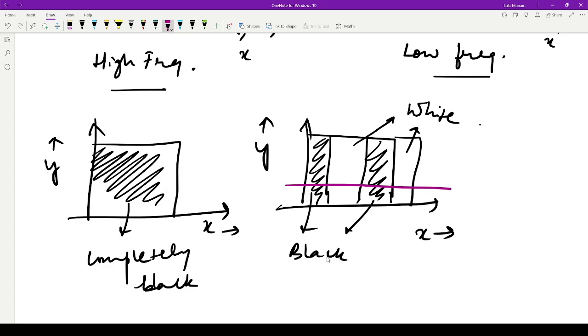But if the image looks pretty similar, the frequency component is low. For instance, an image of a sky, if there are no clouds, will mostly contain low frequency components. But an image of a street has so many elements that it will create high frequency components.